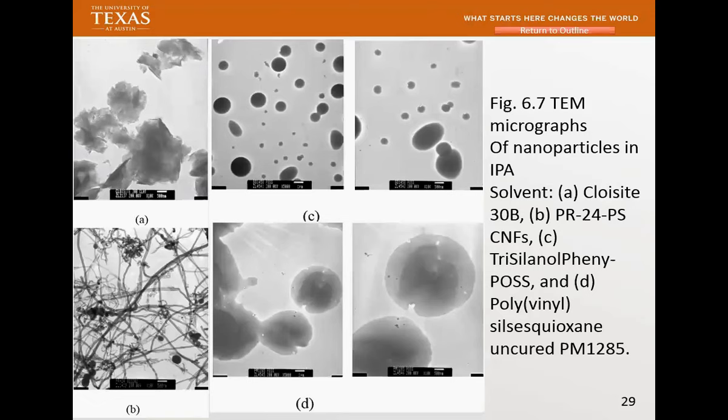All these are different types of nanomaterials we use in my research, carbon nanofibers and polymer fibers. When you buy them, they're all entangled. You need to break them out a little bit and disperse them. But you don't want to break them down totally, because then you lose the length.